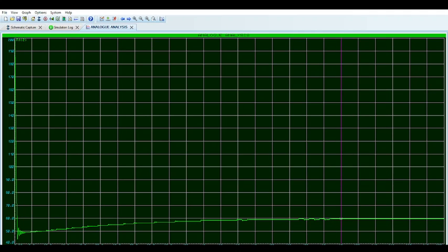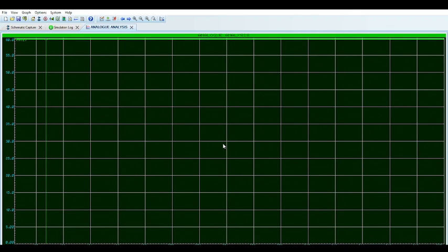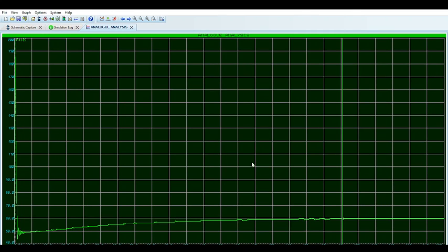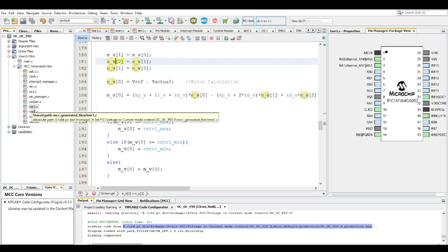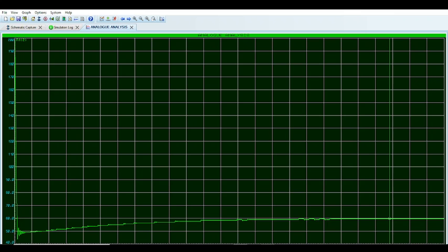In a basic example, almost like a teaching moment to understand how this works, this is just fine. Obviously, you can make it faster if you want, by tweaking it, like I said, by increasing the Ki and increasing the Kp proportionally as well, until obviously the system goes unstable.